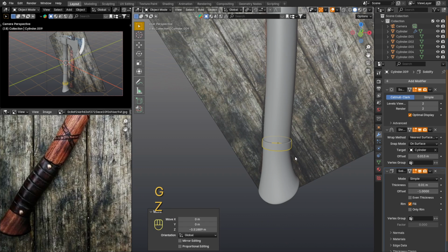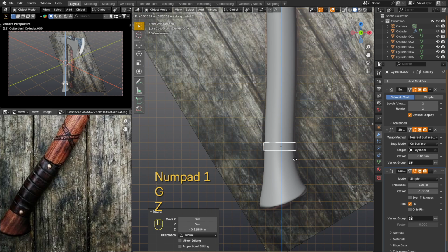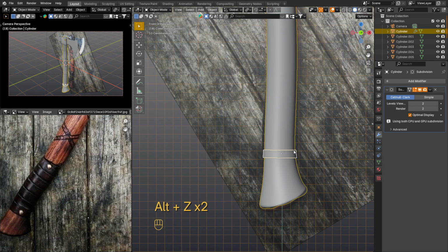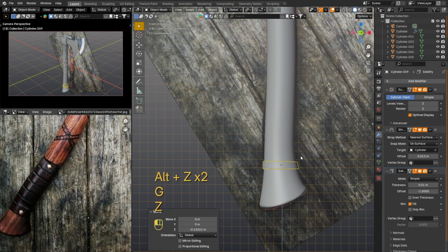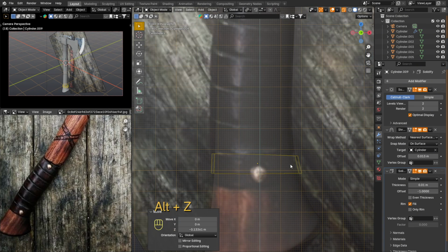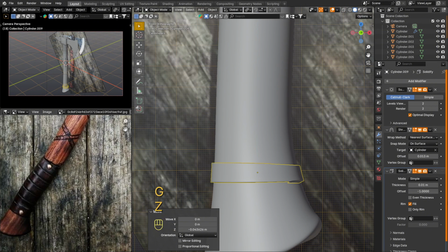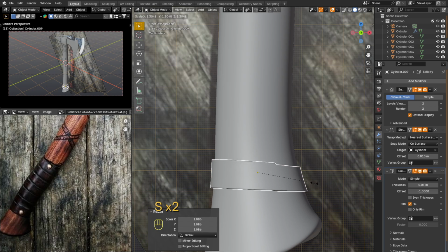Now if you take this element and lower it down the handle to the place where the handle expands, you can see that it repeats the shape of the handle. If the geometry is damaged, it is easy to fix by simply increasing the round elements in diameter. And now the Shift-D combination duplicates the round elements as shown in the reference.